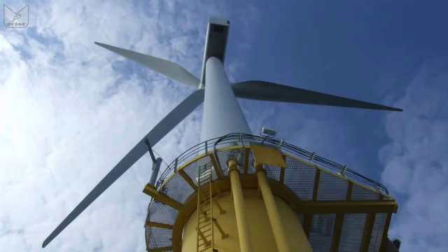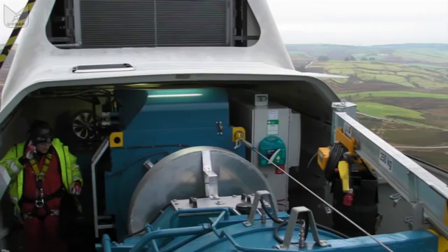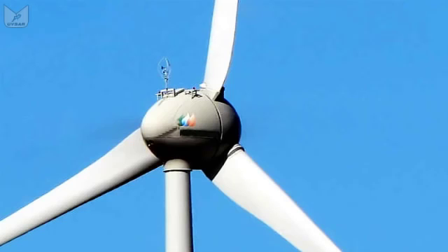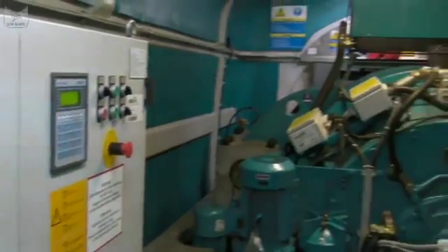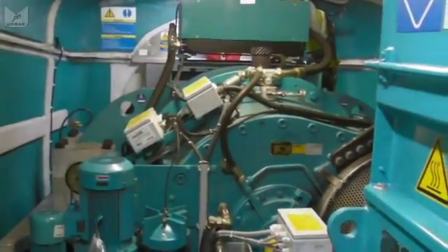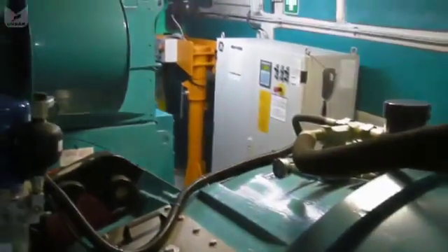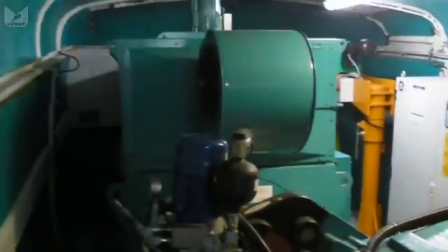The layout of a multi-megawatt nacelle is again more variable than for a smaller version. We always have to have a generator, but we may not have to have a transformer. In a few cases, such as the famous Enercon egg-shaped nacelle, we don't even need a gearbox. They're direct drive. We just have a shaft linking to a motor, and then lots of extremely complicated electronics to condition that power for connection to the grid. But in most cases, we need the same as we needed in the small turbine. Gearbox, generator, possibly a transformer, all in a fiberglass box.